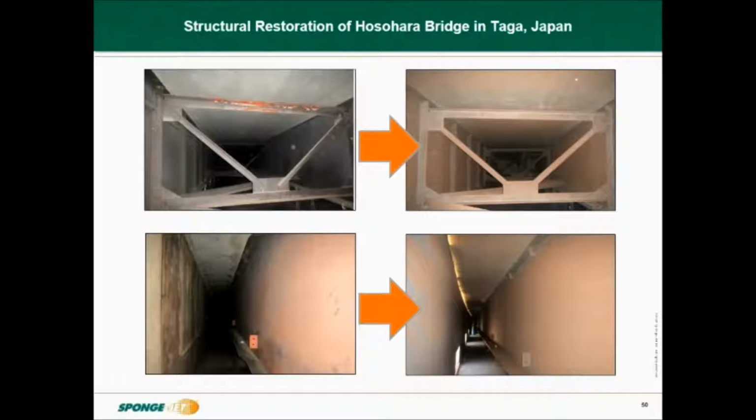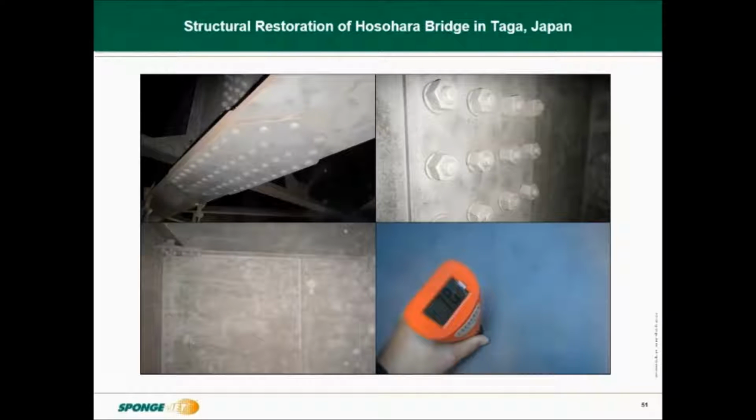Some of the before and after shots of the cross members, and below, the main support beams after blasting and before coating. The before painting shots and the DFT recording after they recoated the structure.